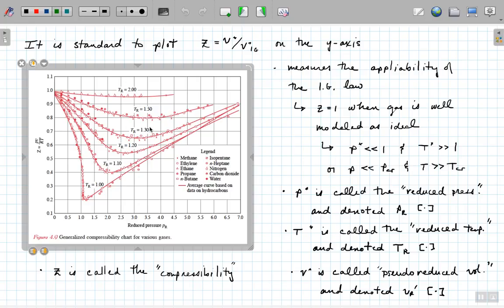So these are actually the values that we ought to be using for the compressibility factor. What I had shown before is what comes out of just using the van der Waals equation, or excuse me, the Redlich-Kwong equation of state for approximating V. In any case, this is the compressibility chart, and so the value of Z being close to 1 means that we are good to go to use the ideal gas law. Z far away from 1, we should not use the ideal gas law.